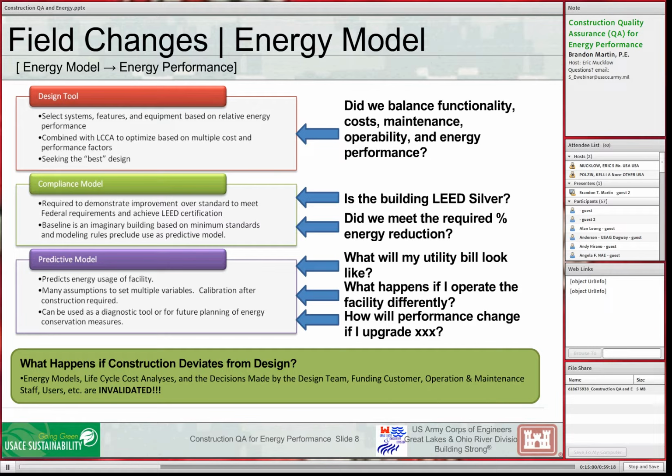So to be useful, after construction and after the facility has been used for a while, data is collected and that model is recalibrated to reflect reality more closely. Those models can help you determine what your utility bill might look like. You can use it to determine if the facility is operated differently: if I change the schedule, if I change the occupancy from everybody coming in at 7 to everybody coming in at 6, what does that do to my energy usage? You could also look at performance changes if you add energy conservation measures.